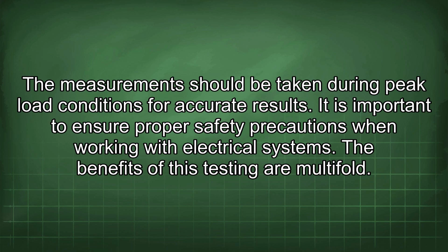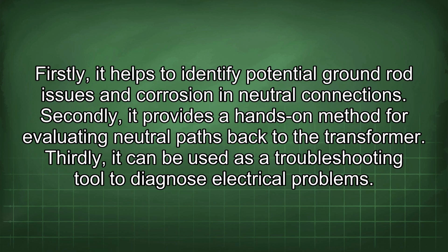The benefits of this testing are multifold. Firstly, it helps to identify potential ground rod issues and corrosion in neutral connections. Secondly, it provides a hands-on method for evaluating neutral paths back to the transformer. Thirdly, it can be used as a troubleshooting tool to diagnose electrical problems.